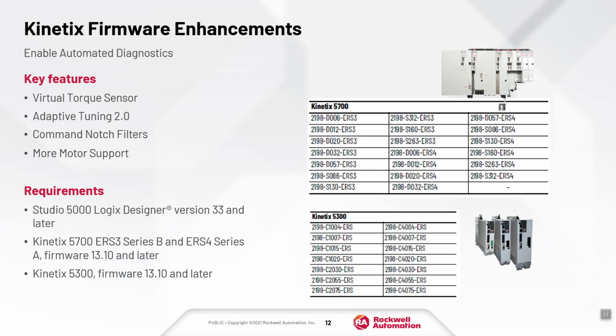We've also updated our ability to provide adaptive tuning on the fly with the 2.0 release of that firmware. And we've also added the ability to provide not only one command notch filter, but now up to 4 notch filters that can be defined per axis.